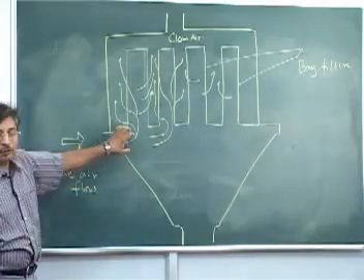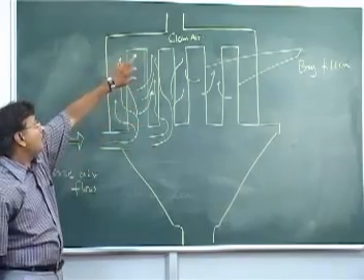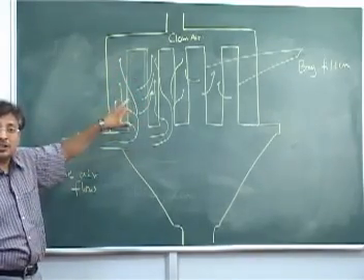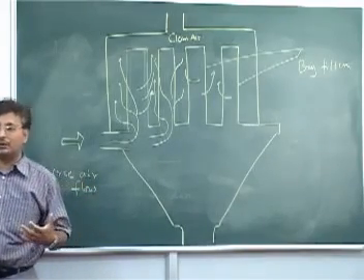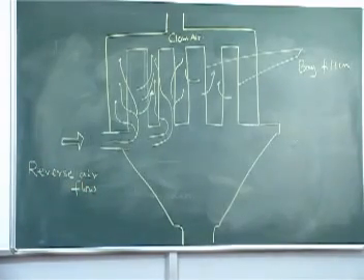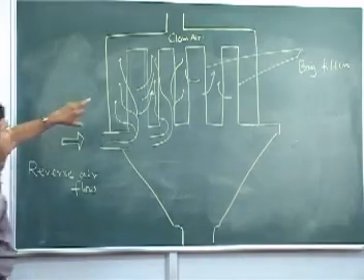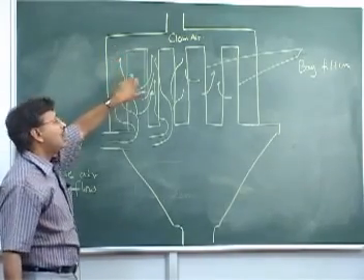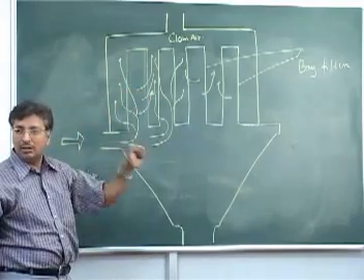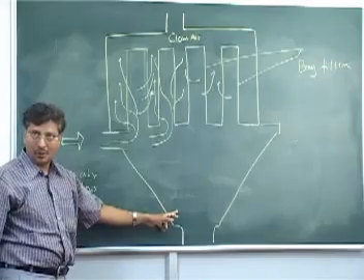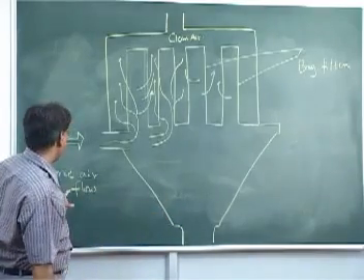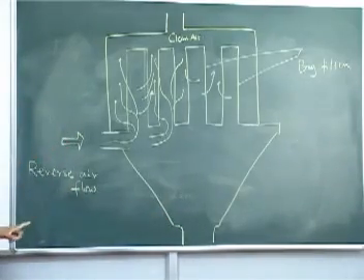You stop this one from here. Make the flow of the clean air reverse. We will have some kind of compressed air and things like that. So you make the flow reverse. Now the flow is from the outside to inside. So that will dislodge your dust, and the whole dust will fall into your hopper. So that is what we call reverse airflow.